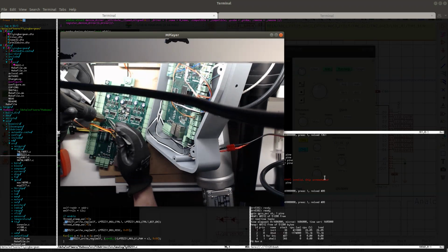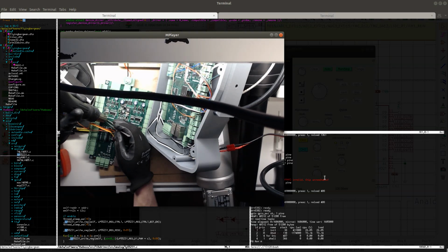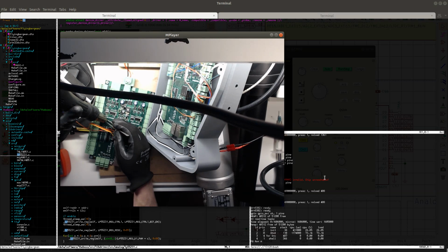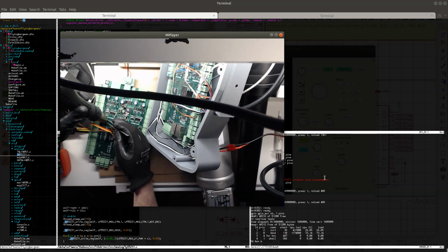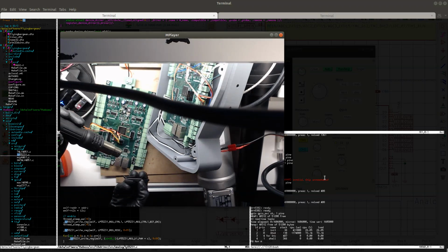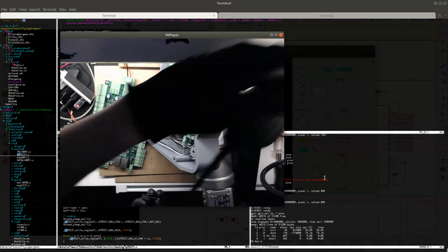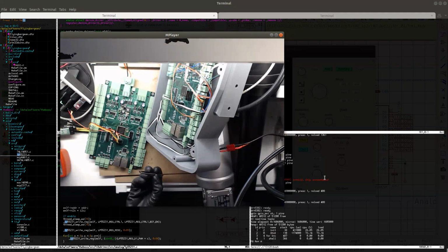And even though it looks like the board is connected to the serial interface, it actually isn't connected. The power isn't connected. So it's just ground and signal. Okay, these are removed. And it looks like maybe, yeah, a few pins again. Same problem like on the other board. A few pins that don't have any solder on them.